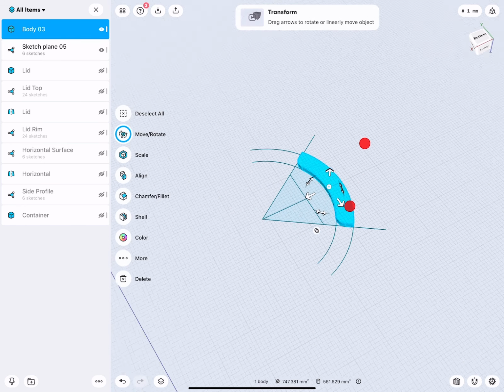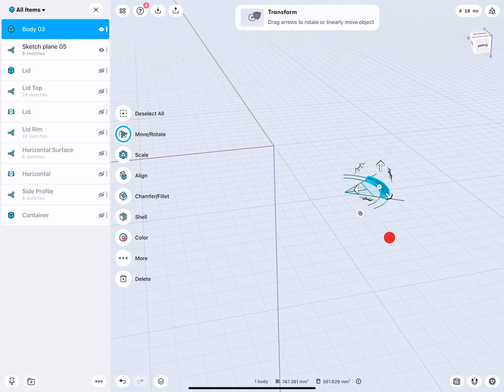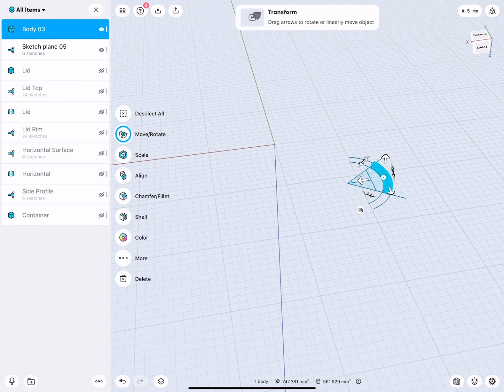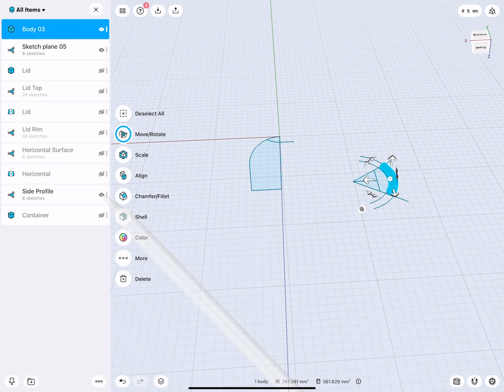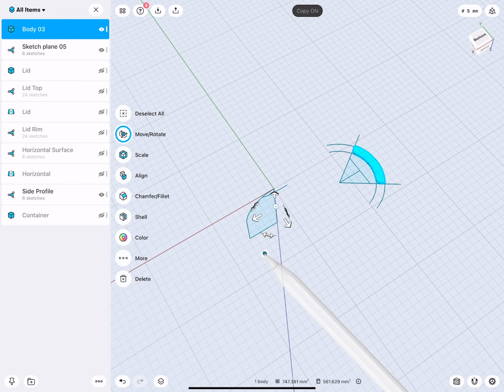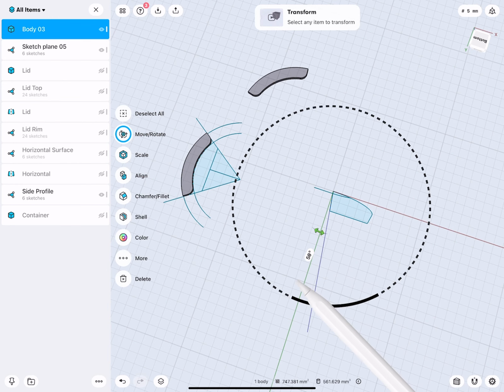We don't have to give this a name because what we will do now is we have to do another copy and paste and rotate. So move the 3D widget to the world center. It's a little bit rotated. Now you see that. So maybe show a sketch, then it snaps to this line. Very good. Turn on the copy command and let's rotate it.